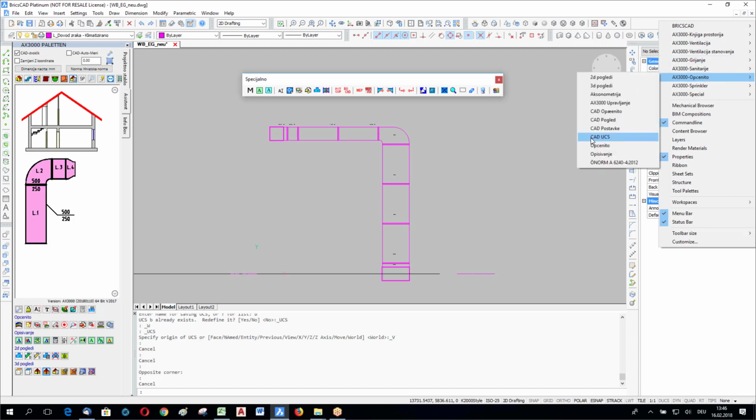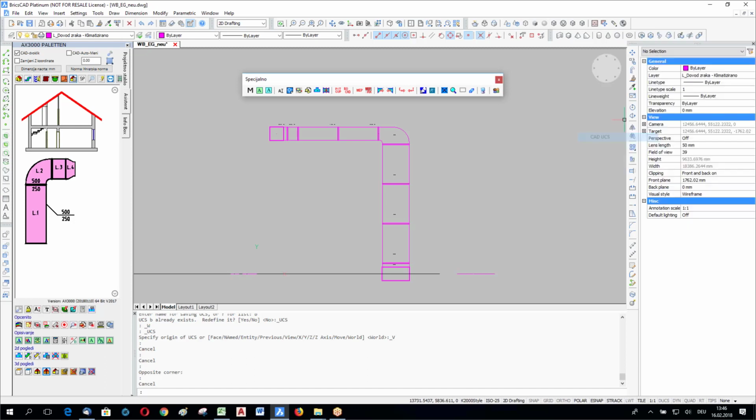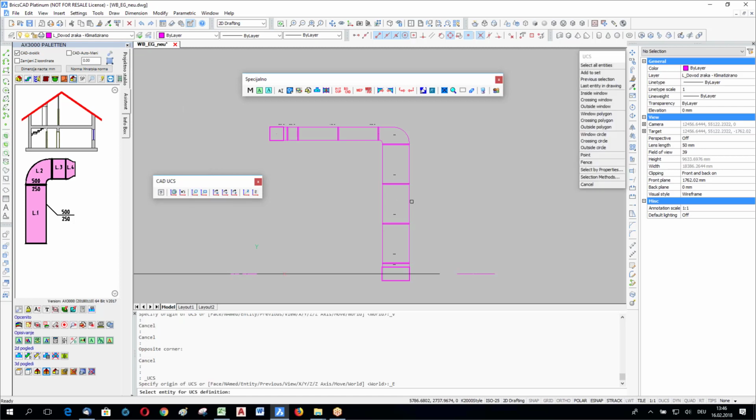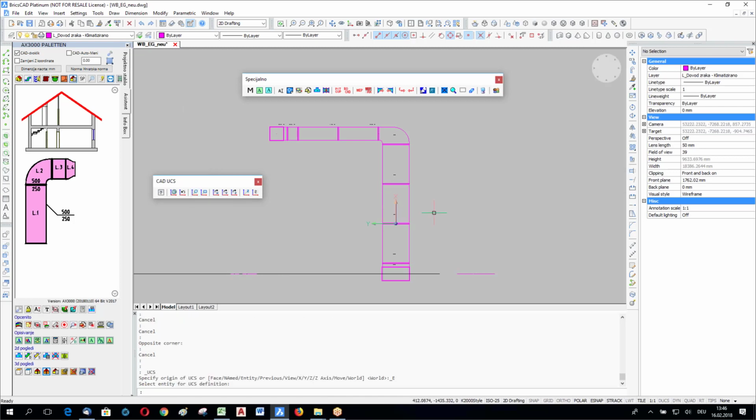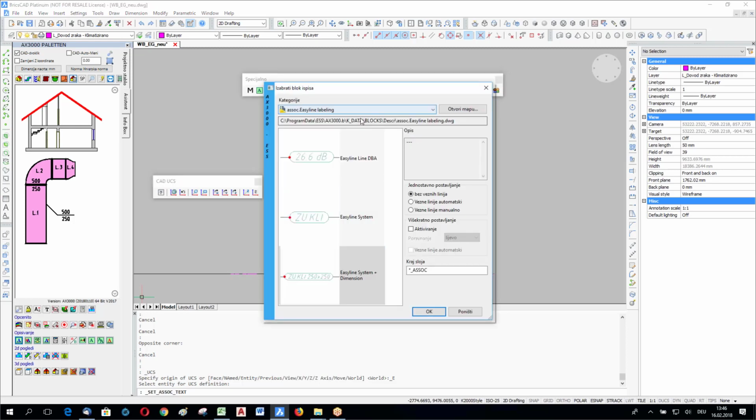You will find a coordinate system function, in the same group you have in AutoCAD. There's UCS1 or UCS2, and one of these is called coordinate system to an object. In this situation I use a duct. Depending on this, my X, Y and also the Z coordinate level is placed in the same orientation as the duct. And so you can use, for example, the associated labeling function to label dimension or flow rate or whatever.